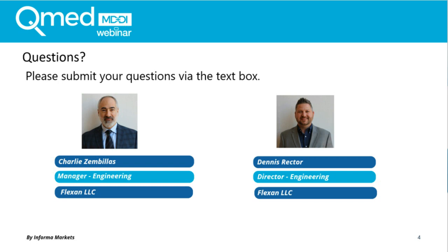So as far as VOC, if you were to choose a peroxide cured silicone, there is some amount of volatiles that normally gets flashed off when you post-cure. Generally, with medical grade silicones, we're working with platinum cures, and volatiles are very low or non-existent. All right, thank you, Charlie.